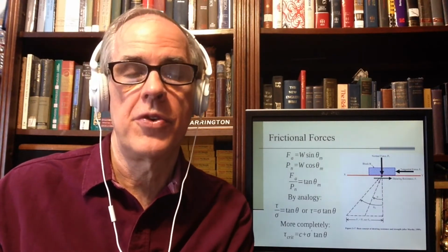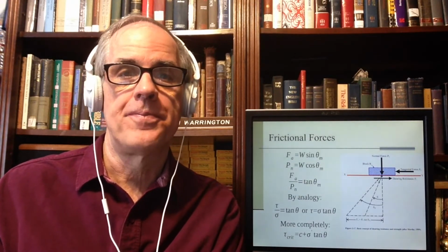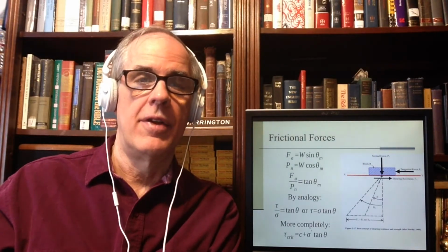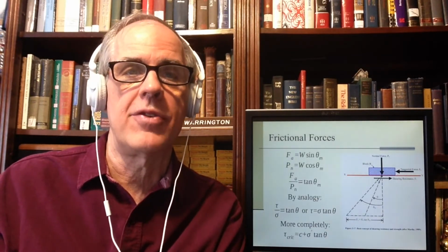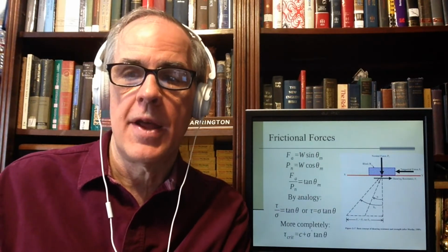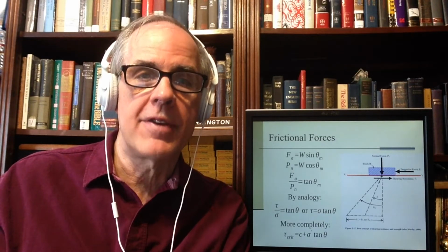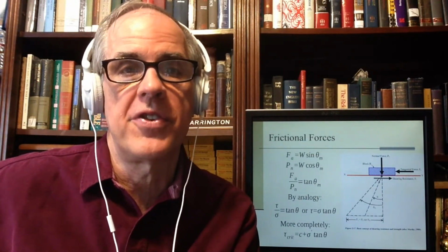Let's start with frictional force. You remember from statics, if you put a block on a level surface, and the weight of the block is usually the normal force, and I apply a tangential force, we know that the maximum shearing resistance force is equal to the normal force times some coefficient of friction.